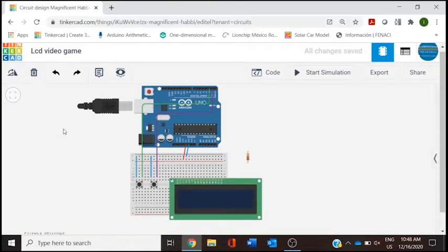Our next component, the last one, is the LCD. LCD has 16 connections, and we are gonna start from left to right with the first one, which is ground. We are going to use all the rails of our breadboard, and the pins can be connected either way on the LCD or on one of these pins. So I'm gonna start with this one. I will do the wiring from here and then going all the way to ground.